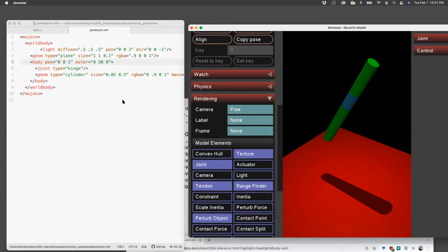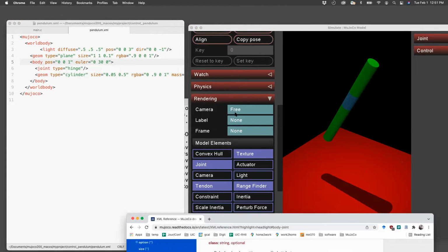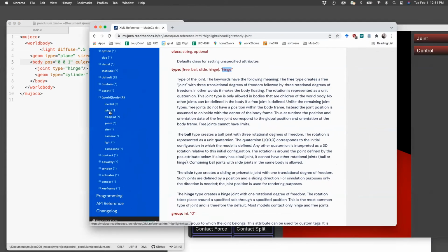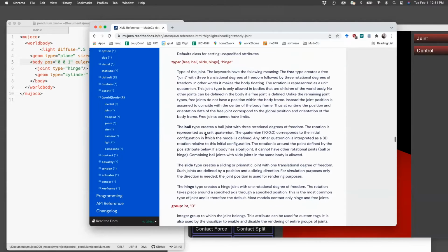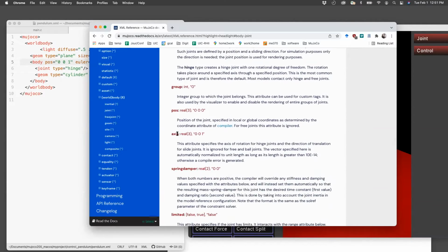So what I'm going to do is choose the joint axis, and I can do that through the joint option. It should be something in the way joint is defined. So let's just go back to joint. So we chose the joint, but we need to choose the axis. So here's the axis. It looks like the default is along the z-axis as we saw. We want to change that to, let's say, the y-axis. So it'll be 0, 1, 0, indicating that the axis is along the y-axis.